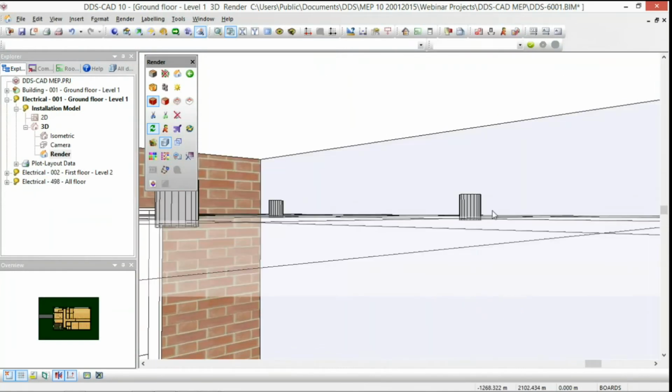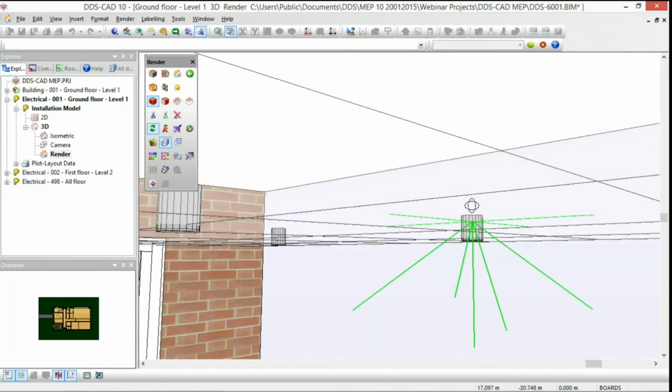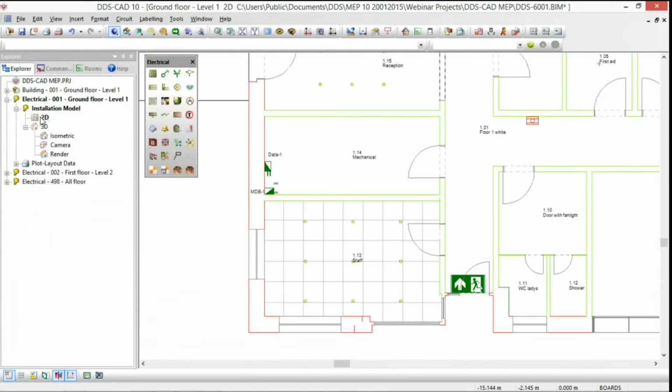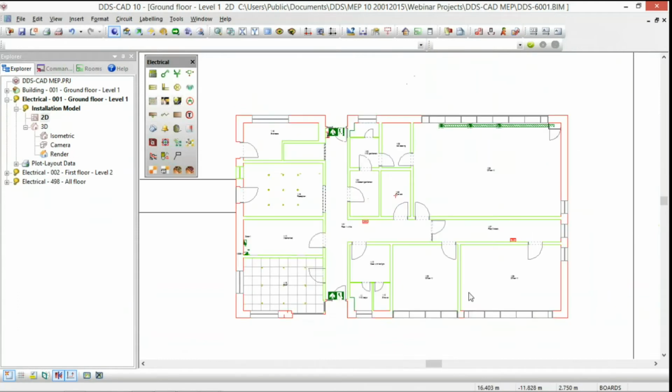There we position the lamp fixtures flush mounted into the suspended ceiling. Of course, we can have flush mounted and wall mounted, meaning that with a wall mounted function of lamps, they will be placed on top of the suspended ceiling. Now, if we change the suspended ceiling by height, of course, the lamps will be changed automatically.